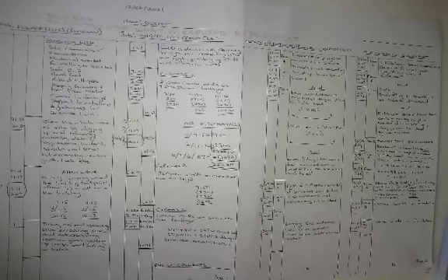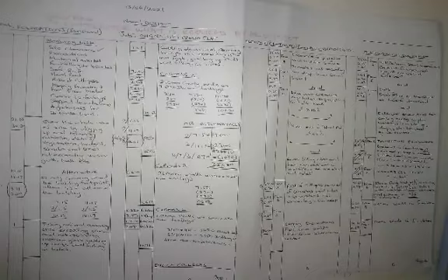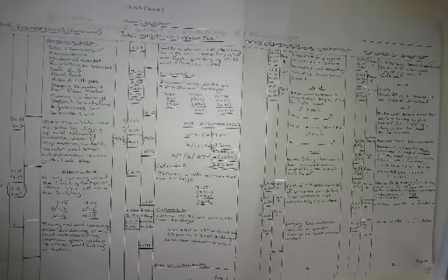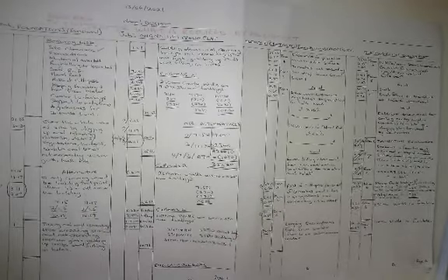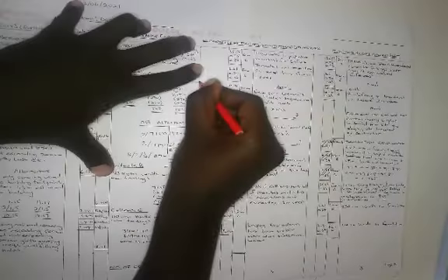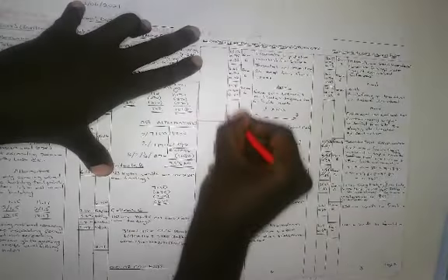So that's the reason for doing it: risk of collapse. Remember, once you disturb soil and you dig through it, it doesn't hold together anymore. It becomes a bit fragile, so it's prone to collapsibility. It can collapse. So if there's someone working in a trench that's 3 meters deep, there might be a possibility that that person may die.